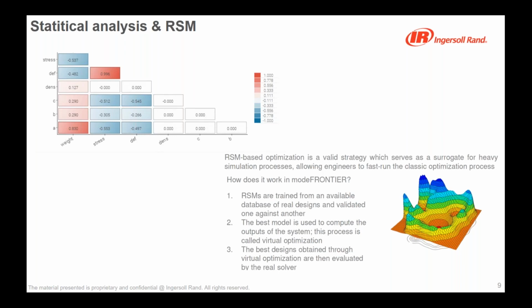The response surface method, on the other side, is an interesting method, but I always say it's also a tough one, and you have to be careful in how to use it. The main reason for that is because the response surface method is just creating a virtual representation of your design space.